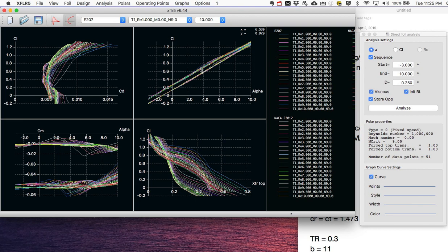You see the lift lines are fairly Reynolds insensitive. And the key thing looking here is I want to make sure I'm getting a good range of lift coefficients. So I'm getting negative lift coefficients here all the way to lift coefficients of 1.2. The range I really need is right here, basically 0 to 0.4, and my data clearly spans that range, so I don't have any concerns about this, and I know my Reynolds numbers will be sufficient. So that's done. These polars are in here.